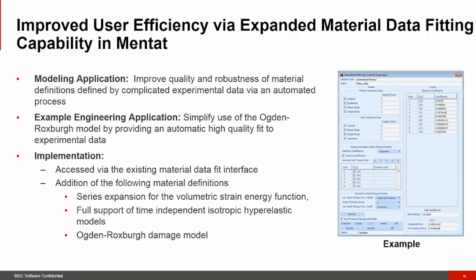Instead of going through the whole operation of taking experimental data and fitting them manually, we're providing an automated method for your benefit, and this makes it much faster, and you can start making a comparison between material models in a quicker format. The previous Marc releases' material data fitting engine was also available and was supporting many models. However, in this one, we've introduced new ones. Various material models can be successfully derived from experimental data.